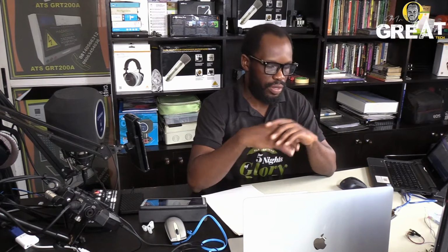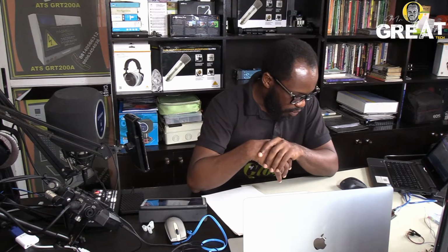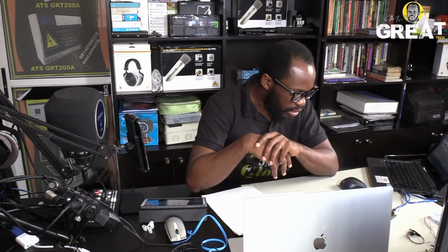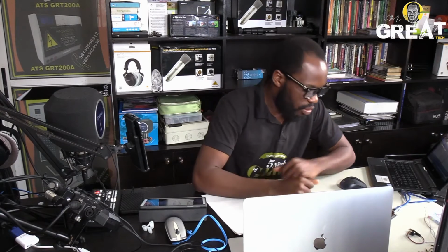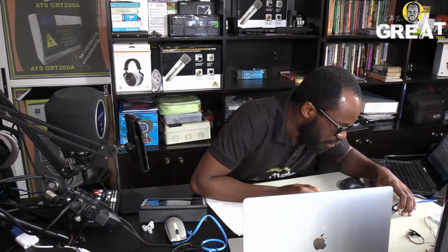And when it comes to pulse width modulation, analog voltages, we have dedicated pins, just like I told you. Pins 3, 5, 6, 9, 10, 11 are pins that you can use for pulse width modulation. These are pins that you can use to write analog voltages. And when it comes to analog read voltages, you are going to use the analog in pins, which are from A0 to A5. That's the 6 pins of the analog in.